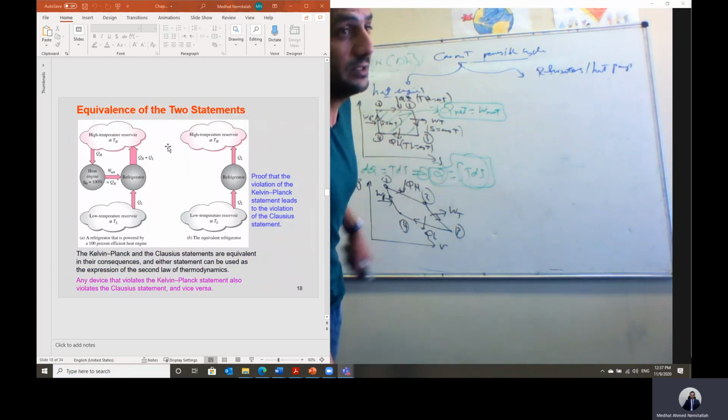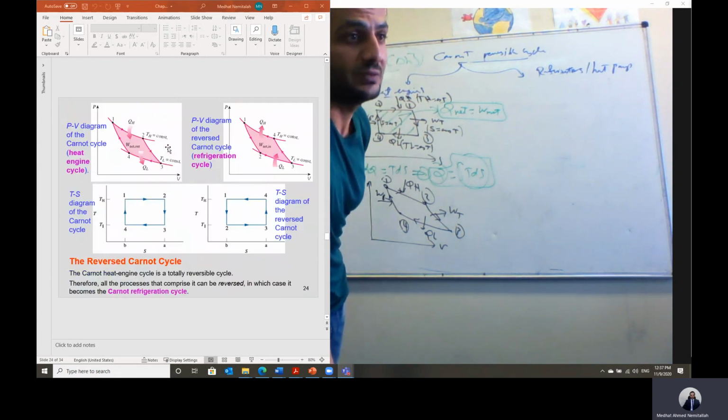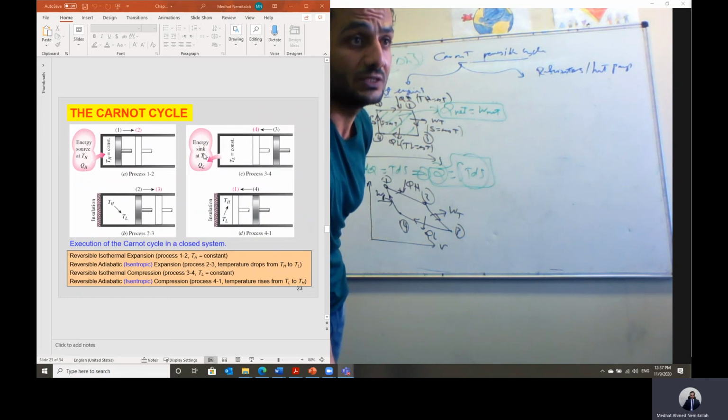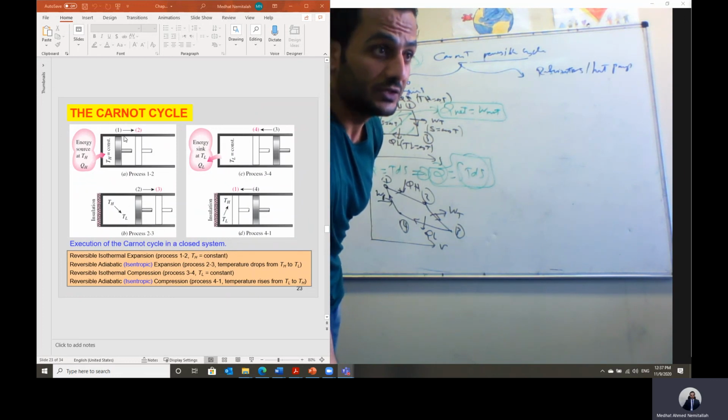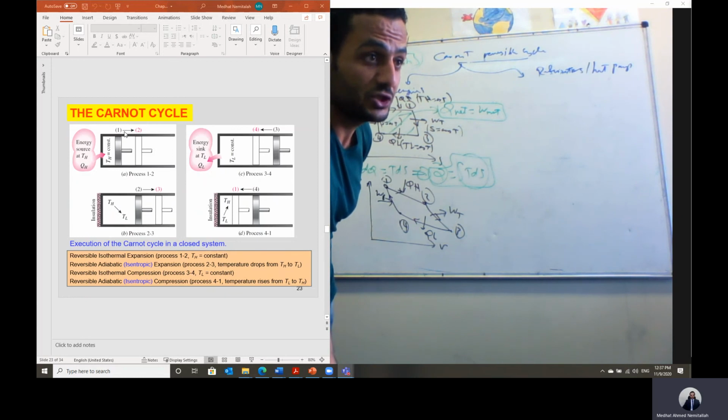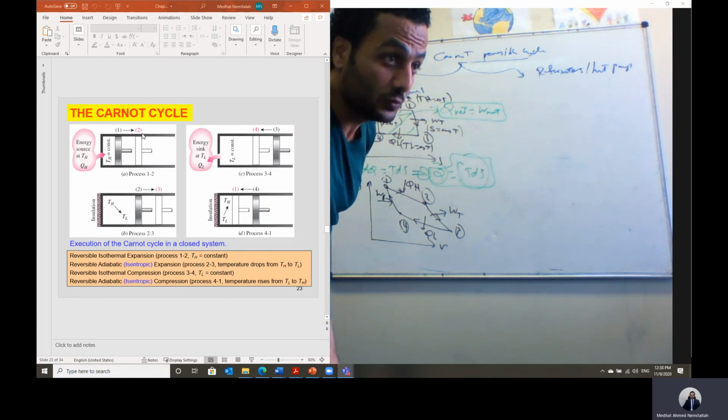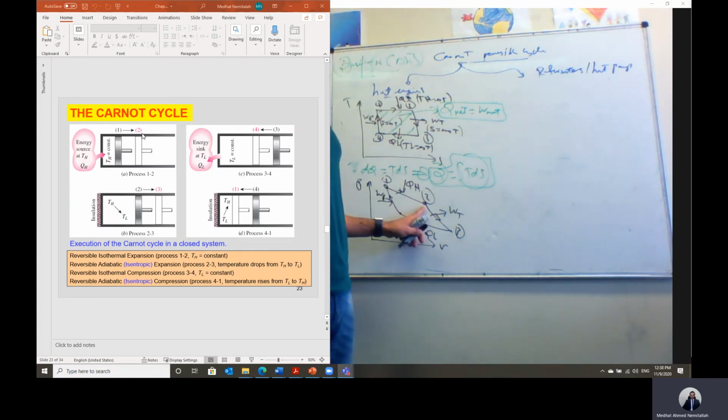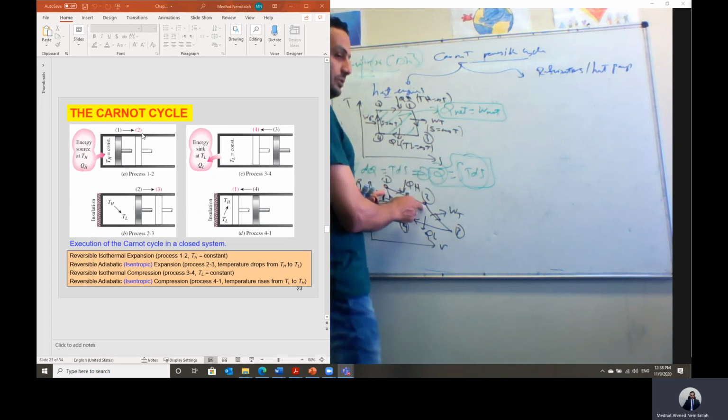The Carnot cycle can also be applied for the case of a closed system when we have a gas in a piston cylinder device. So that means gas in a piston cylinder device, the system is closed. So if we consider this expansion process, let's say heat addition from state 1 to state number 2, this heat addition is isothermal. So the temperature T1 is the same as T2. But if I want to calculate the heat transfer for this closed system, I will not say Q dot equal to m dot delta H. This is not an open system like the boiler. It is actually a closed system.